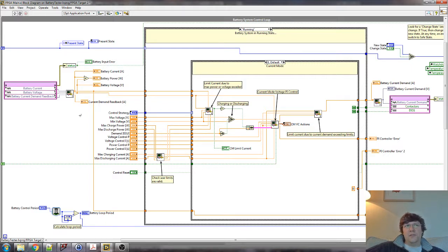Of course, Nyquist and noise are two terms that you shouldn't really interchange because Nyquist only applies to periodic systems. And anyway, let's not get into the debate now. But suppose you're doing EIS and you want to go to very high frequencies, you might want to do some burst mode work. That isn't written into this, but you could. There's no reason why you shouldn't, and you could make it an extra mode on your FPGA that sets up a slightly different sampling setup.